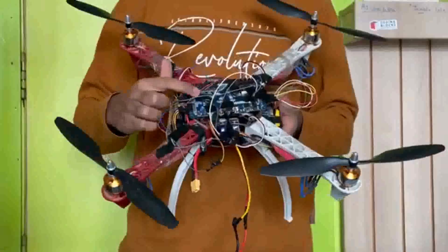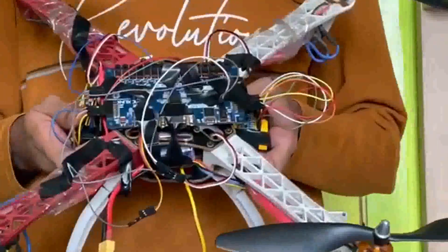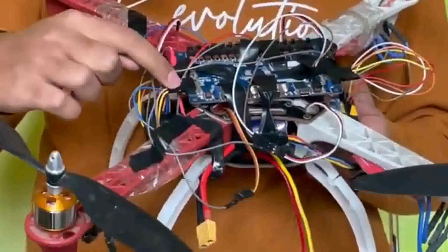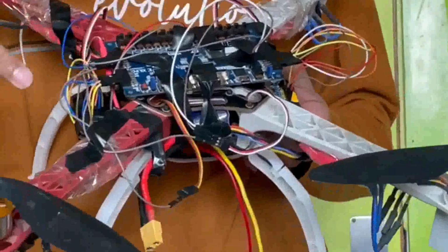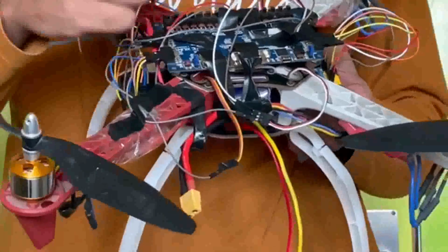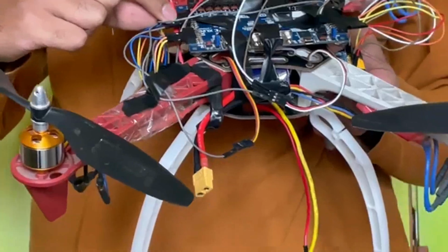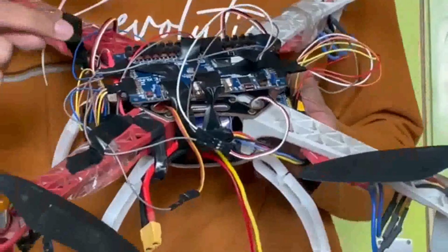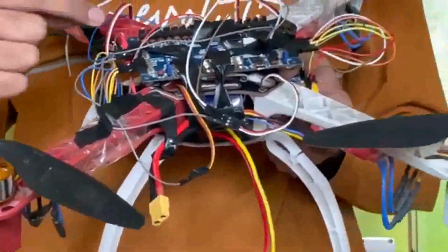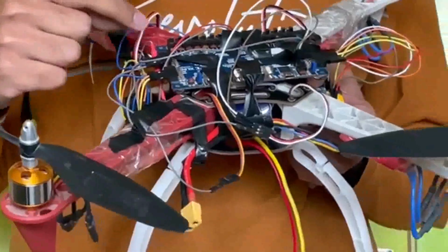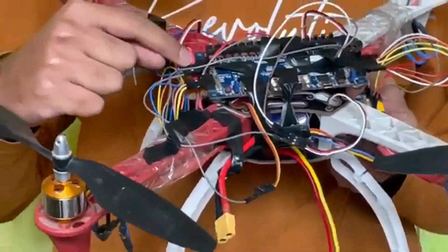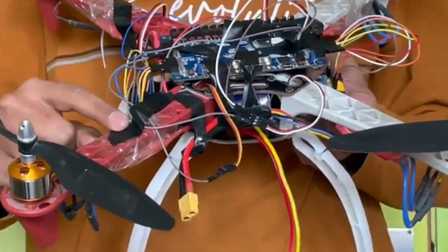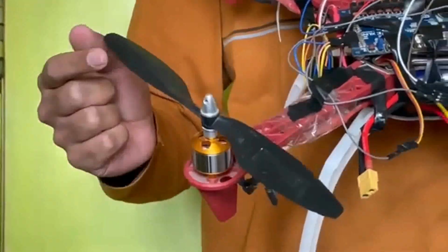Then we move to the FPGA. This is a Basys 3 board from Digilent. It has an Artix-7 FPGA. So this FPGA has several input and output pins. Now we are using these input pins to receive the values from the transmitter via the receiver, and then we also take as input the values from the sensor, the MPU 6050 gyroscope, and then we calculate the required response to the given inputs, and the values from the FPGA, the calculated output, are fed back to the electronic speed controllers in form of pulse width modulated waves. These pulse width modulated waves, based upon the duty cycle, drive the motors at the required speeds.